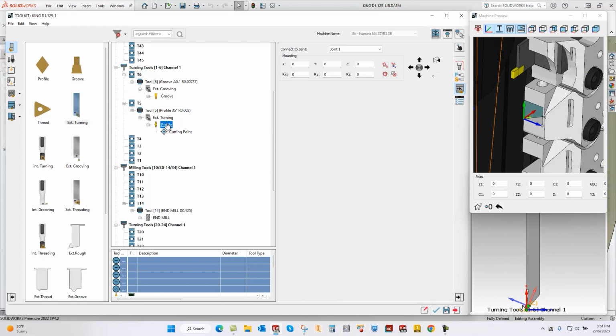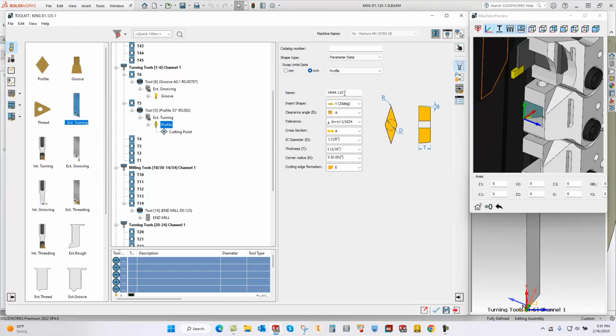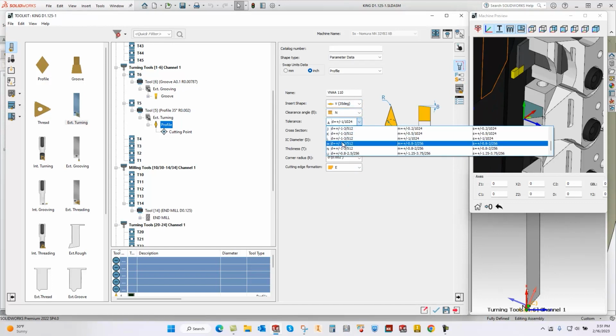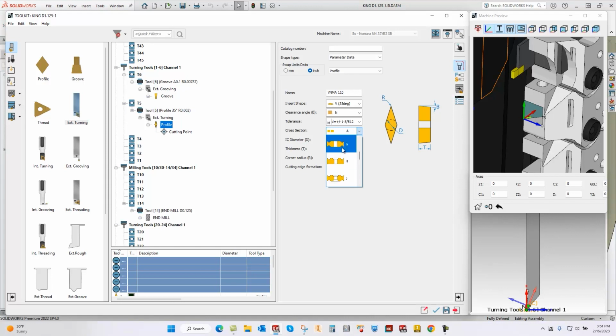So we'll click on Profile, and you can literally pick it from a list. V, we'll just grab an N, M, let's go do a G, and we'll do like a, I don't know, this may be a little big, but 3, we'll do a 2, and maybe a 0.2 here. This one here, that'll be fine. So we have a VNMG 320.2, and if you'd like, again, you could also just type it in up here, by the way. I wanted to show you the drop downs.